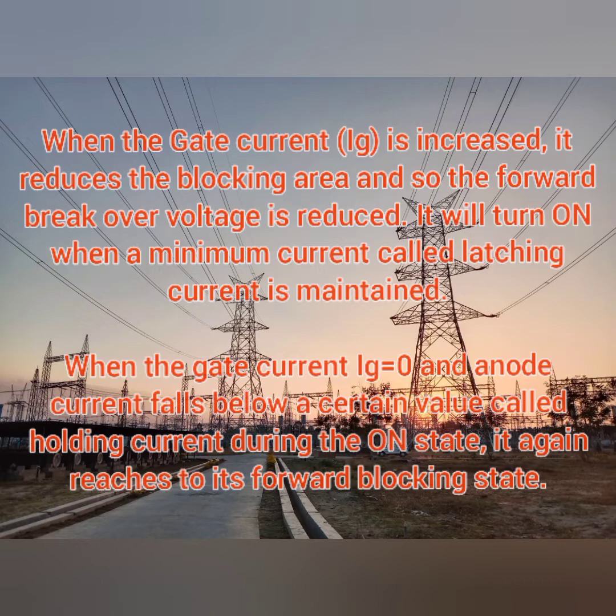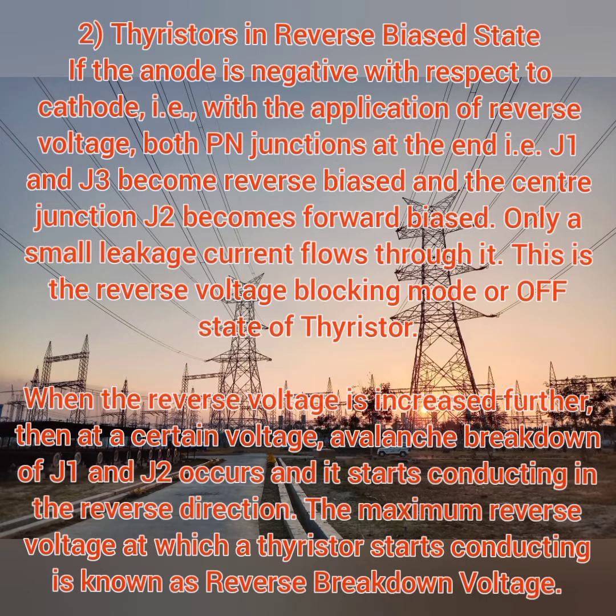So when the gate current Ig is equal to 0 and the anode current falls below a certain value called the holding current, it means there will be no conduction during that state. These are the two main conduction paths.